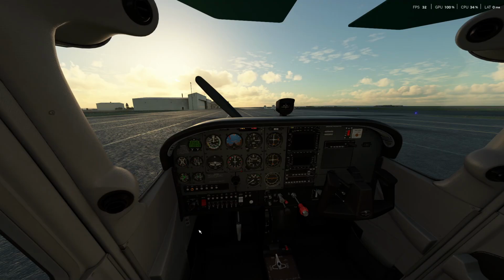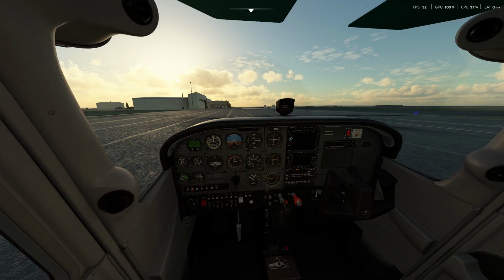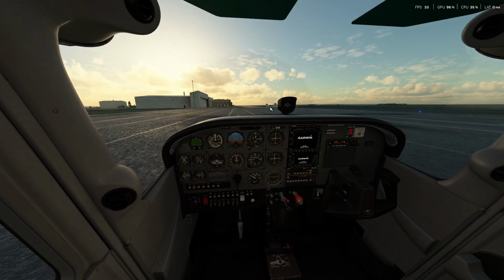Alright. So oil pressure is rising, nav lights go on, and throttle's at about 1,000 RPM here. Alright, so before taxi checklist: fuel selector, left tank, avionics master switch, turn on, radios, we can go ahead and turn those all on. There we go. So all the nav equipment and the communications equipment there is turned on.